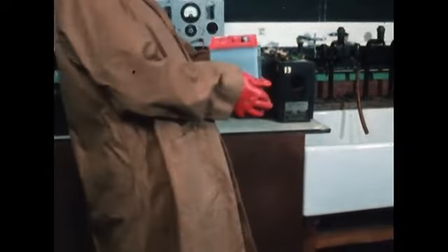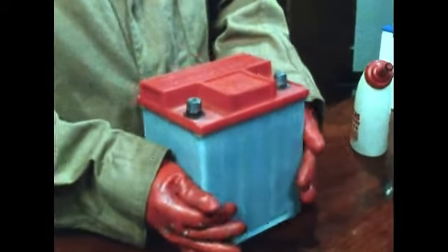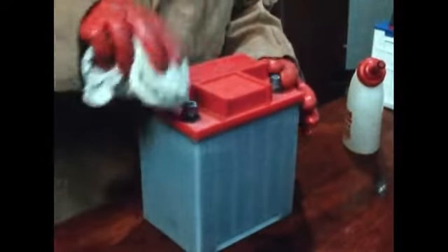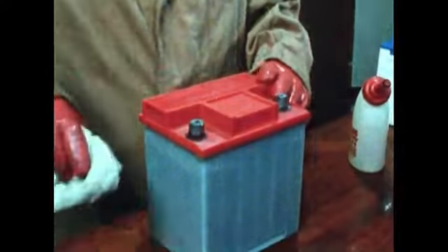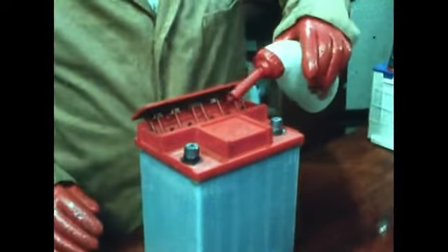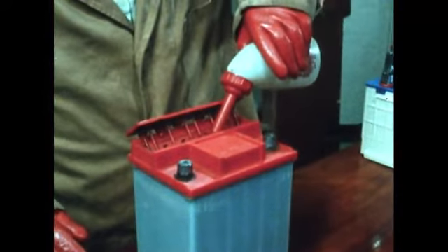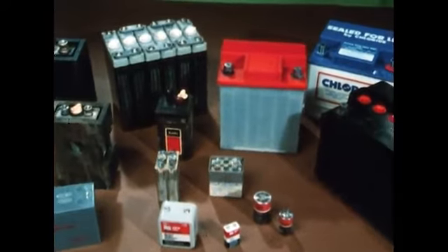Looking after a battery is fairly easy. You handle it carefully for a start and you keep it clean, particularly the terminals and connectors. Keep adding distilled water, and don't let it go too long without recharging. In this way, your batteries will give you long and faithful service. And before we leave the subject, we'll talk about an important point.